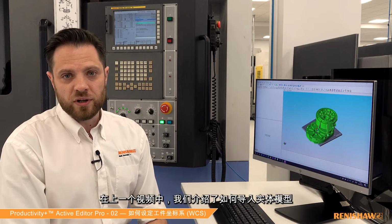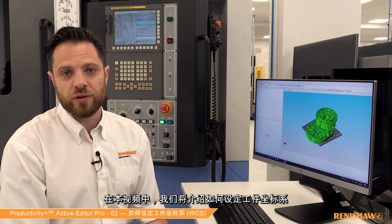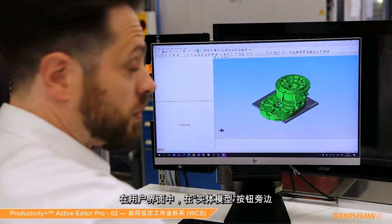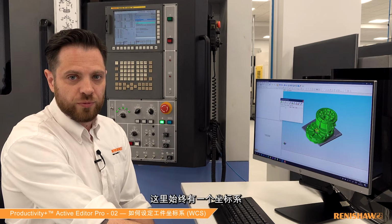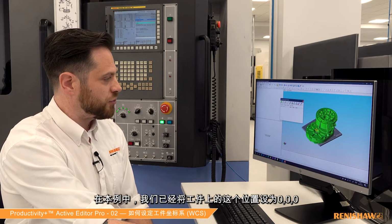So last video we looked at the import of a solid model. This time around we're going to look at how we can set the work coordinate systems. As we see, we have our model in from last time. If we go to the UI, next to our solid models button, we have a coordinate systems button. If I click on that, that will give us this dialog. This is our coordinate system manager. We'll always have one coordinate system in here. There's always one that's set up, and at the moment we have that set to that location on our part at 000.